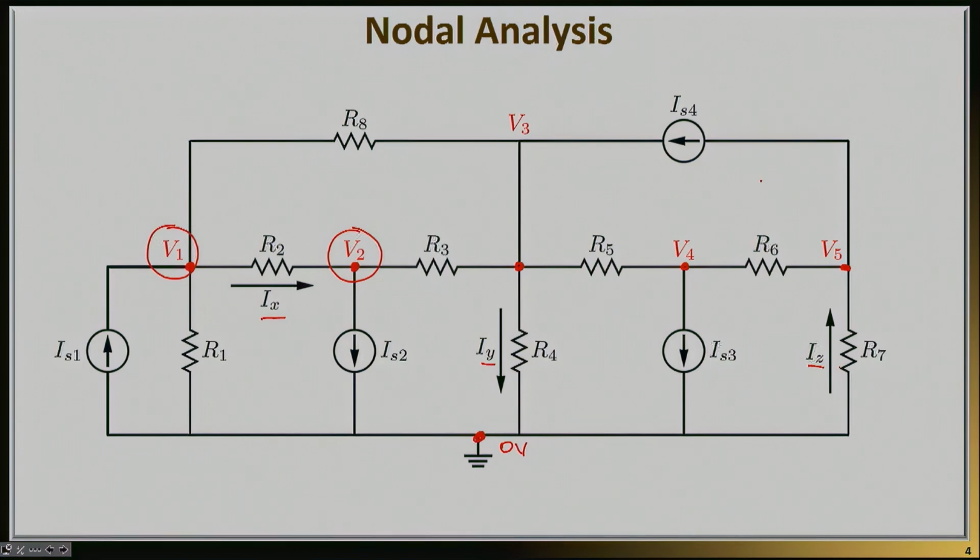Now, let's take a pause for a minute, and we will go ahead and find what these nodal voltages are, but let's say that we did know them. So let's say we've performed nodal analysis correctly. What's the next step? Well, once you do know the nodal voltages in a circuit, the currents, the powers, any voltage drops that you want to find will reveal themselves immediately.